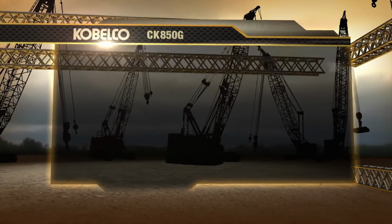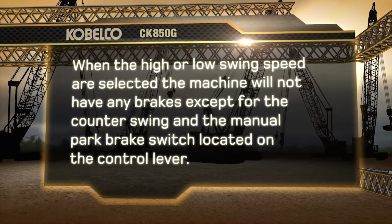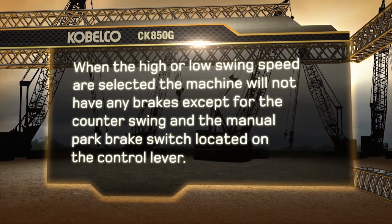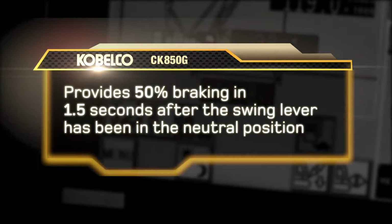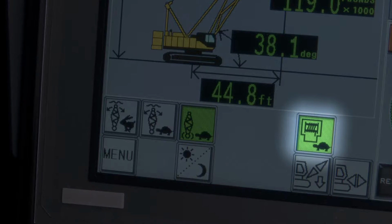When the high or low swing speed are selected, the machine will not have any brakes except for the counter swing and the manual park brake switch located on the control lever. And the third icon is the slow speed swing with braking. This setting provides 50% braking in 1.5 seconds after the swing lever has been in the neutral position. These are followed by the work mode select icon.